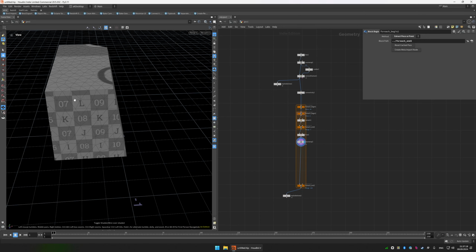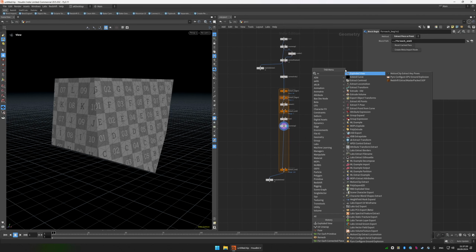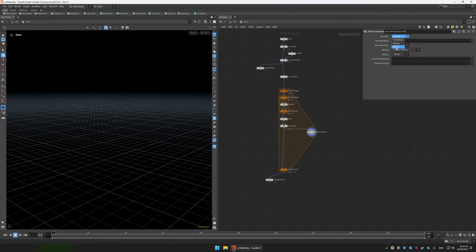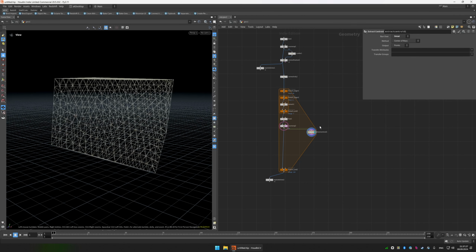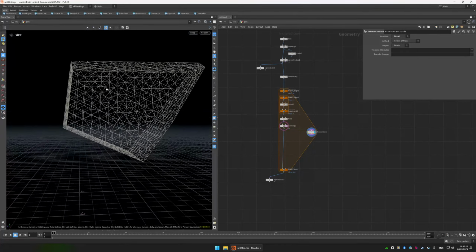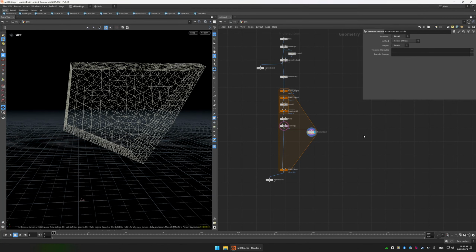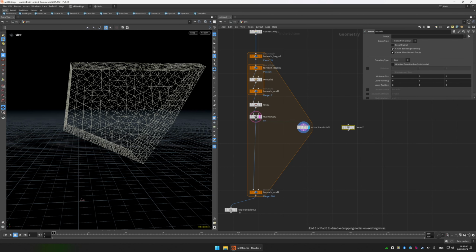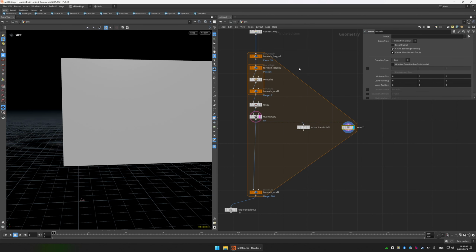Now we want to turn this into the sphere. We're going to use extract centroid here, and we're going to run this over detail. It will put a point inside of the centroid, there are different ways you can get this point. You can use a get bbox center and stuff like that, but I like to use just nodes here. And then also we're gonna use the bounding box node, bound, and then set here the sphere.